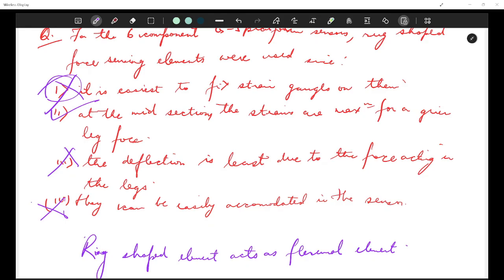Okay. The other option is it cannot have dynamic isotropy. Dynamic isotropy means all natural frequencies are equal. So, for a traditional 6-6 Stewart platform, mass distribution is not symmetric enough. Inertia coupling exists, right? And the stiffness matrix is not perfectly isotropic dynamically. So, natural frequencies do differ. That means dynamic isotropy cannot be achieved in the traditional configuration. That is why we saw in the lecture as well, in probably the last part, that optimization was required to approach dynamic isotropy. So this statement is true.